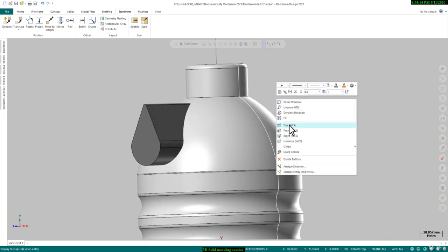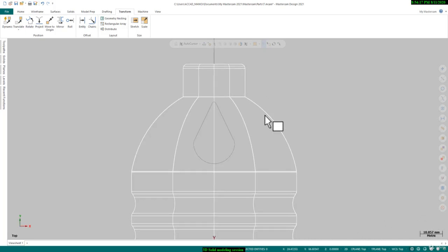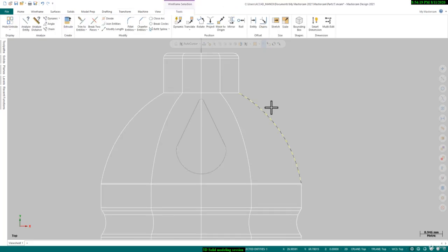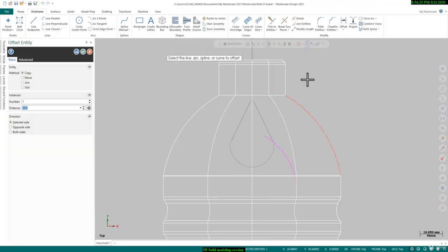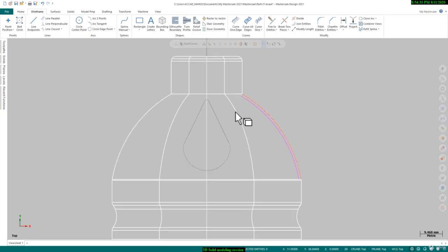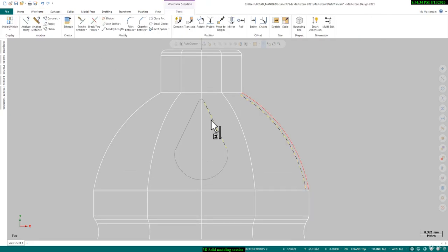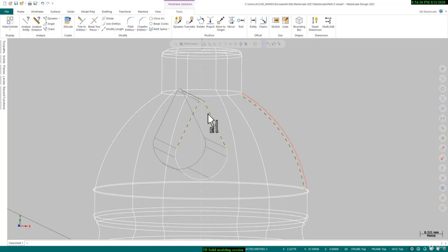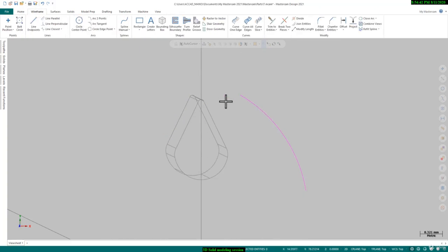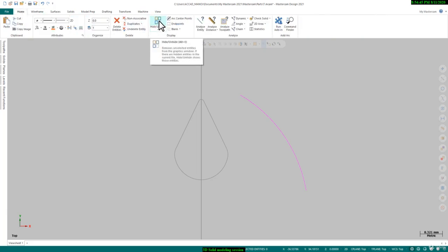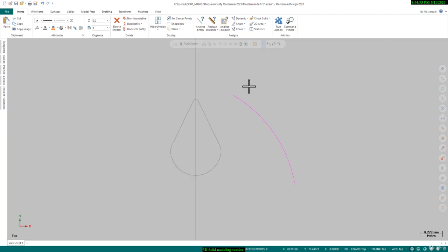Okay, so we need maximum 1 mm of depth from this face, so we will select this curve, and then we will offset it, wireframe and then offset from this point to this point. I will keep it 1 mm only, depth value will be only 1 mm. I will select that solid also, not wireframe, only solid. Select the solid and then say Alt plus E, means hide command. So you can hide all other entities and keep the selected entities on the screen, so that will be very easier to work. You will not get disturbed.